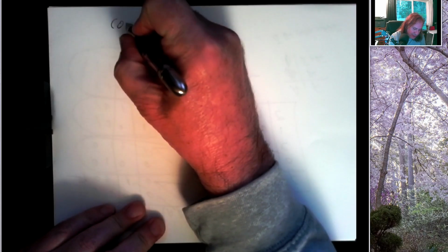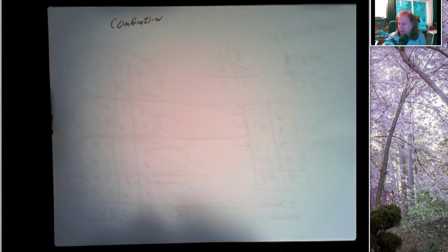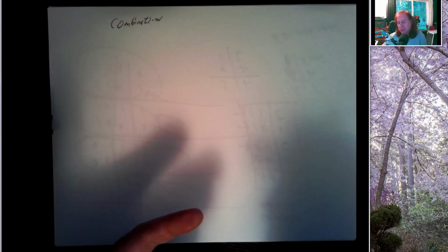All right, so we're going to move into the second part of the course material now. So far, we've been working with circuits that, other than glitches, we can describe their behavior with a truth table. These are called combinational circuits. They're combinational because the output that they produce is based on the combination of input values. And if we know what the inputs are, we know what the output is. And we can make, for example, a truth table and then look up a particular combination of inputs and in the output column see exactly what outputs are produced by the circuit.